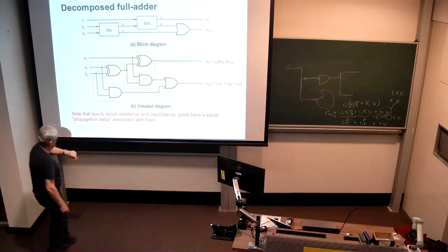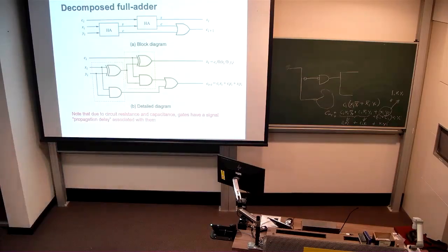One more thing to talk about, and then I think we might just have a break. Gates are made out of transistors, but transistors have capacitance and resistance associated with them. Because of that, those of you that have done a bit of circuits know that there's a time constant associated with charging the gate up or with discharging the gate, when you let the charge go.